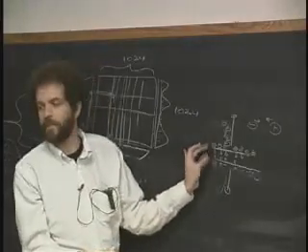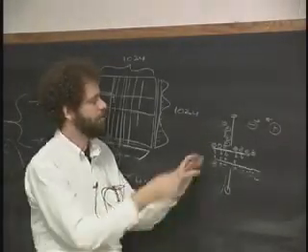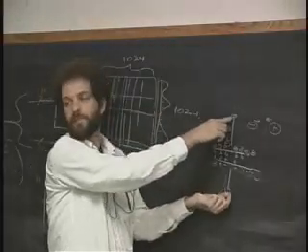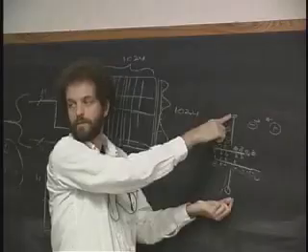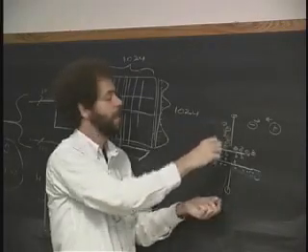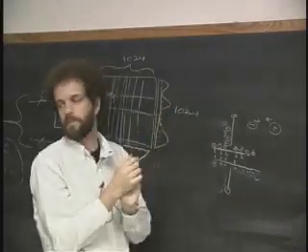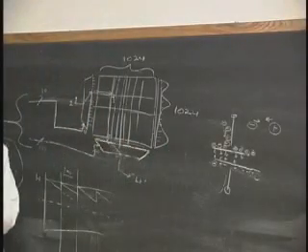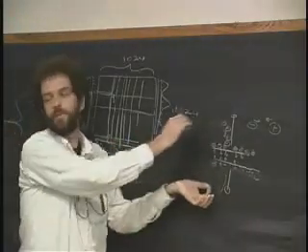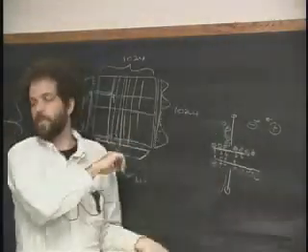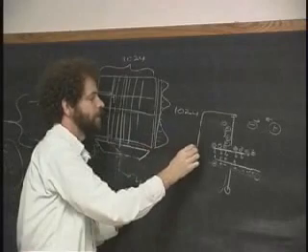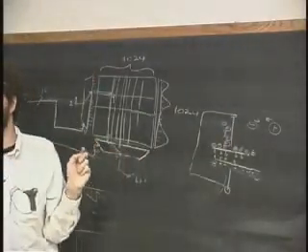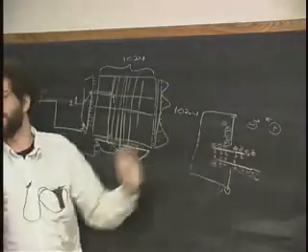If you were to short this out, you get a nice spark, and they'd all find each other. But they don't. And so you can now measure the voltage here, and you'll find that this is negative and this is positive. And there's an actual voltage on this thing. And I can take this and put it in a piece of glass, which is an insulator, and I can walk around all day with it, and it'll hold the charge. And then I can come back and measure the voltage again, or I can suck all the charge out of it by connecting the two ends, or maybe dumping the charge into some other circuit, which is that sense amplifier, and seeing whether or not there was charge.